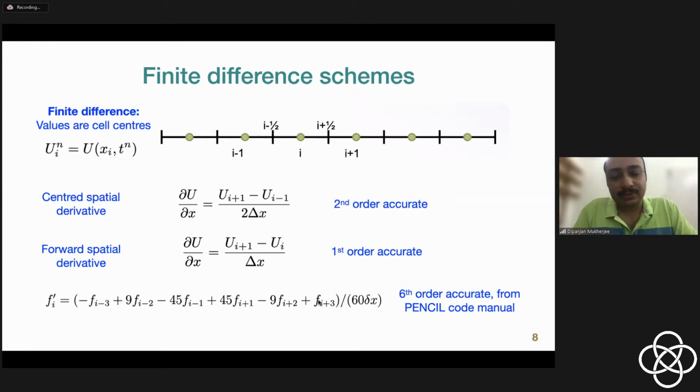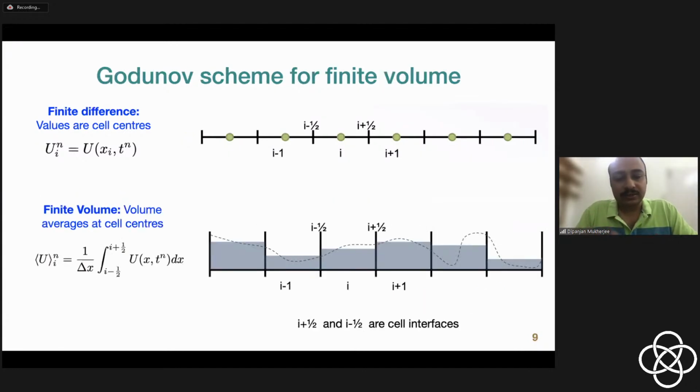because you can easily implement finite difference schemes. The problem with this scheme is if you have some discontinuity, then as you can understand, the derivatives blow up. So this kind of finite difference-based scheme is very good for systems where there are no shocks. For continuous, well-behaved fluid properties, you can very accurately evaluate all fluid quantities. But if you have shocks and discontinuities or sharp changes in your system, where the gradients start blowing up, then you are in trouble. But the conservative form of the equation has an advantage.